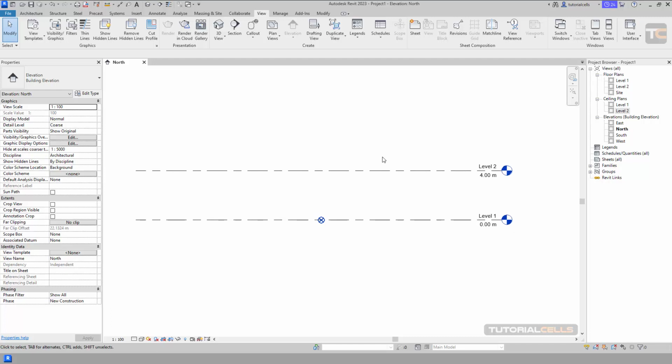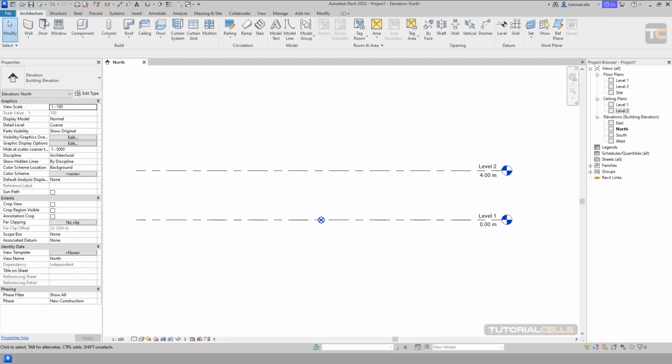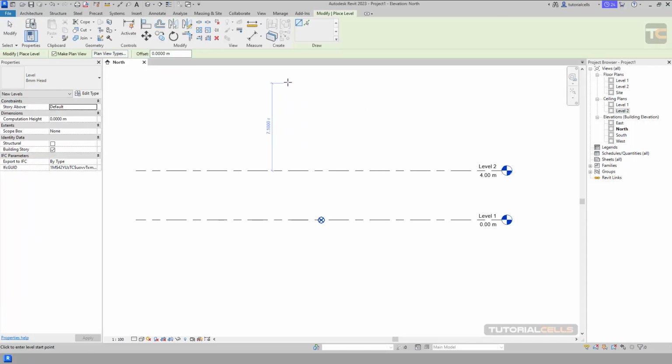Okay. For creating that, we go to architectural and here's a datum. In Revit, creating a level and a grid is called datum. For creating a level, you can click level. If you activate any command in Revit, the modify tab in Revit will be active. These are all the command settings, and from this line to this part are the settings of that. For example, we want to draw something, so you can simply create a line.